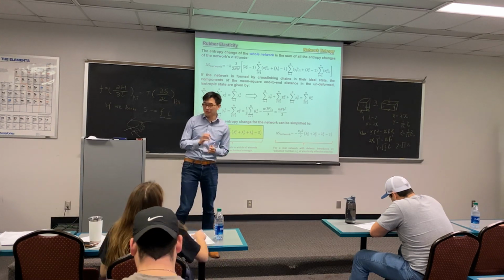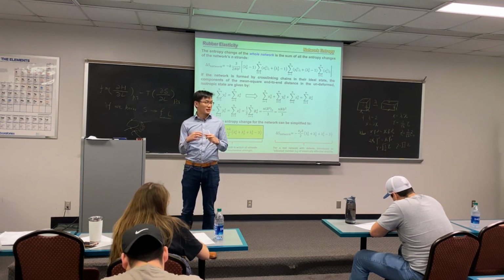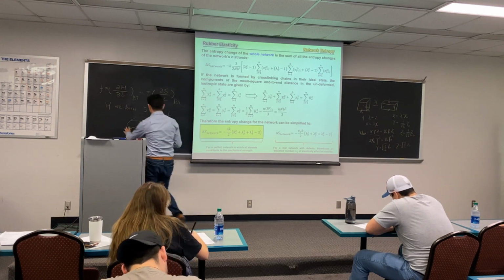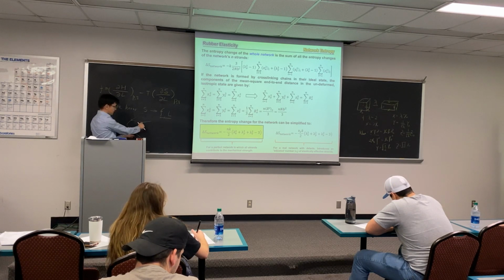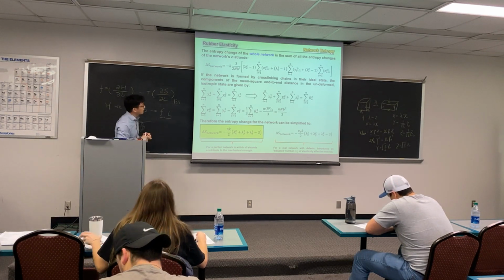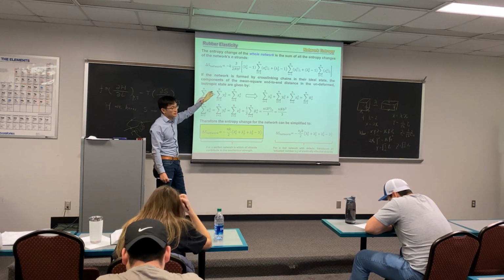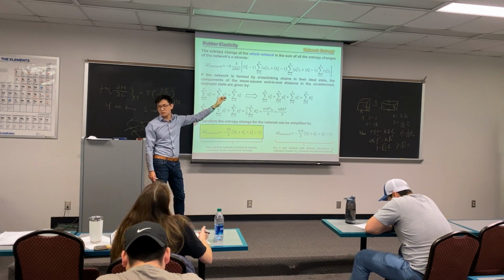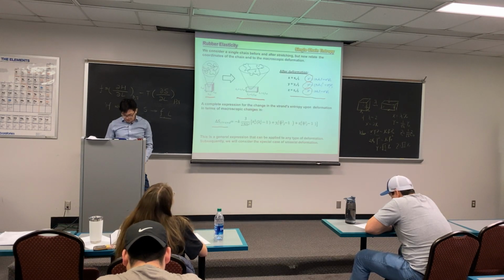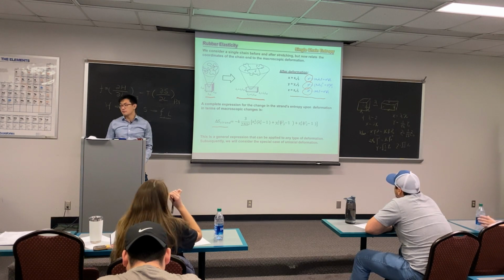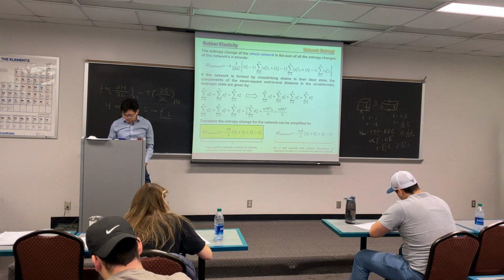So we have talked about single chain entropy. Now, how can we understand when you deform a network? Basically, think about the rubber band where we have a lot of these individual strands fixed between 2 cross-link points. When we deform it, we can basically assume it will be the sum of all the individual strands in between the cross-link points. So the first equation looks very long. It's exactly the same as this equation, except that we are now going to sum up all the individual strands, okay? All the strands are summed between these terms.